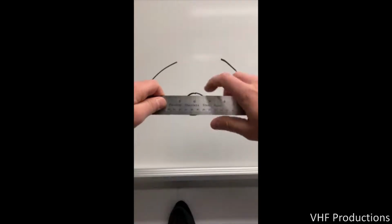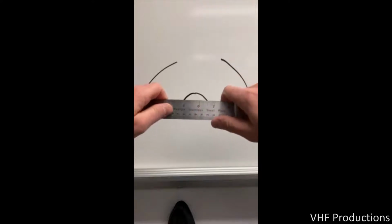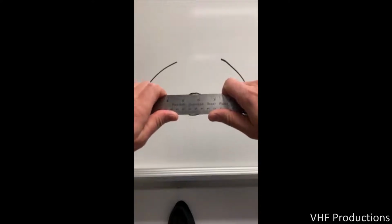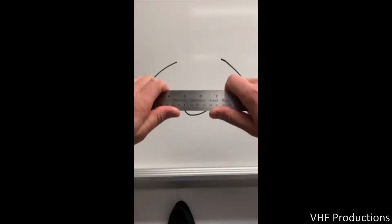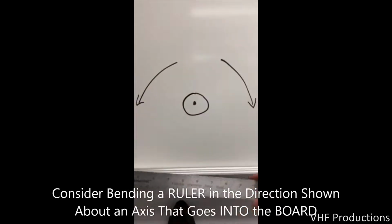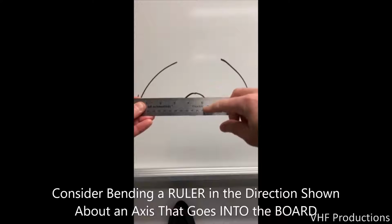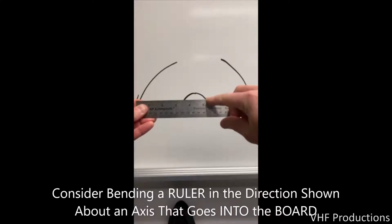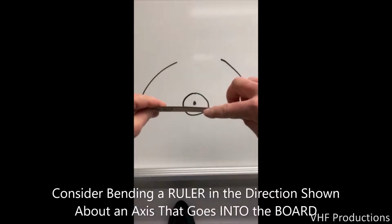However, if we take the ruler and simply rotate it 90 degrees so that we're looking at the flat surface of the ruler with the inscribed numbers, and we now try to bend it in the same manner, you can see how stiff this orientation of the ruler is relative to the previous one. Keep in mind here that we haven't changed anything about the material or even the geometry of the ruler. We've simply changed the orientation of that geometry relative to the bending axis.